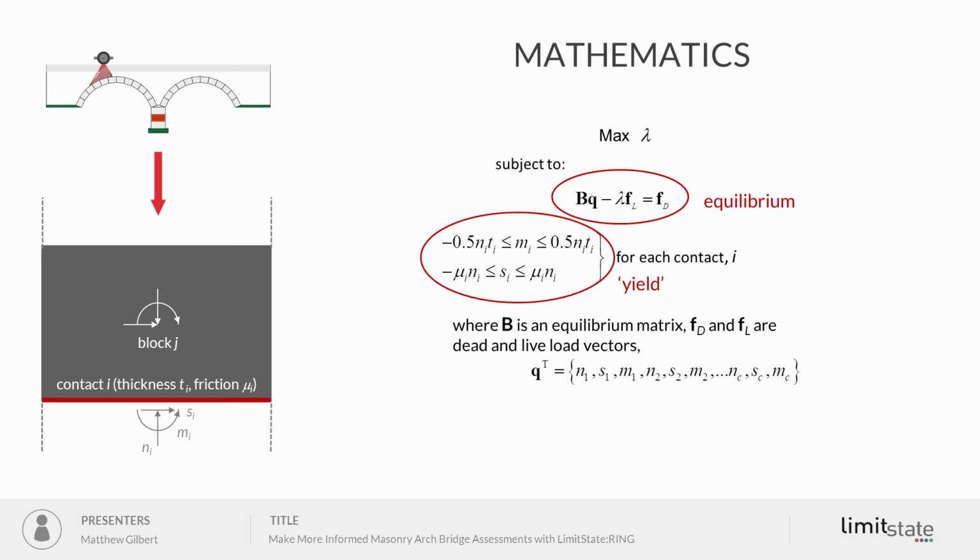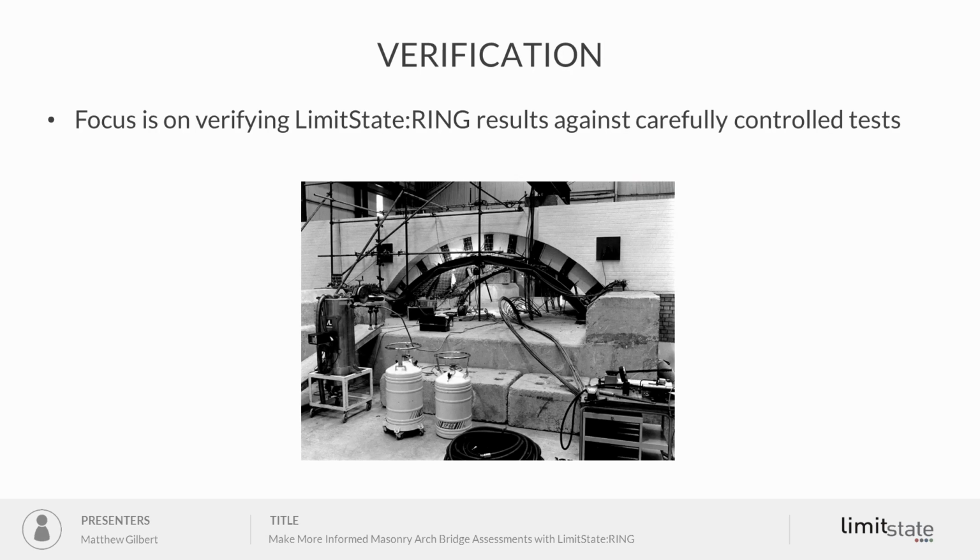But we can also provide limits on those interface or contact forces. So for example, to say that we potentially could have sliding. So we have the shear force. The limit is between the coefficient of friction times the normal force in one direction and also in the other direction. And similarly, we can have rocking failure with the relation above. And it's a nice, simple, quick to solve problem.